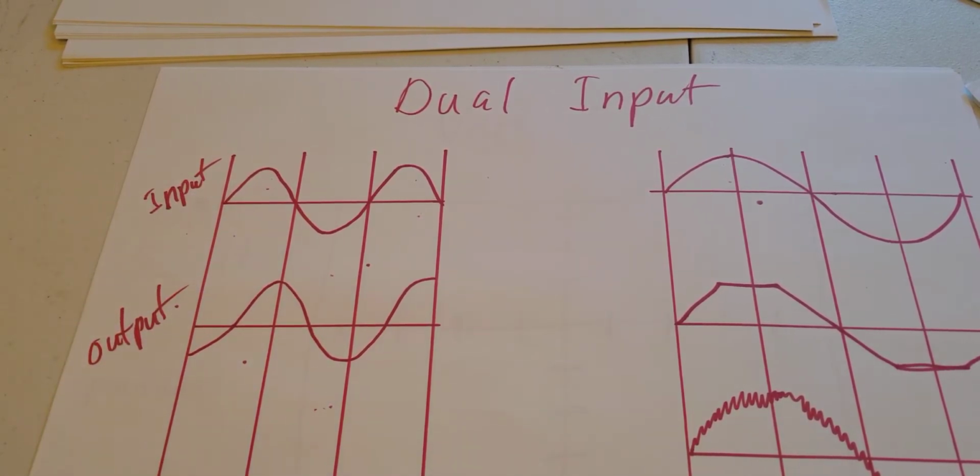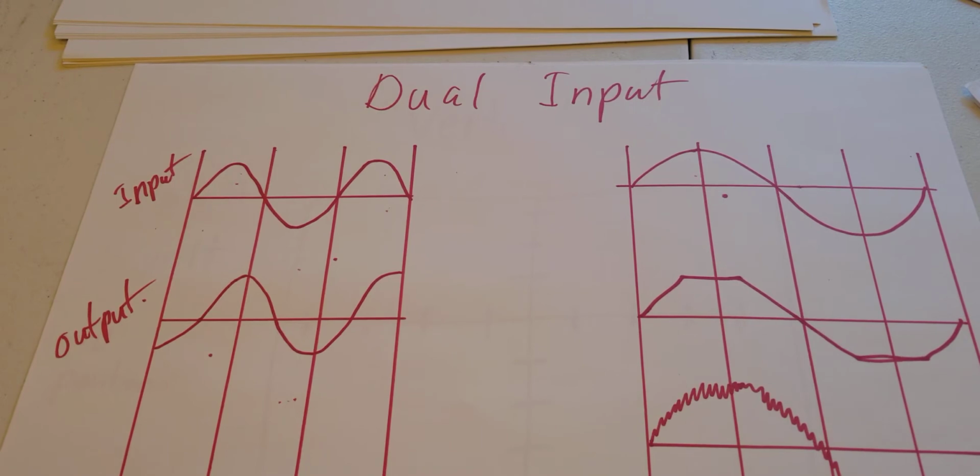So, for example, if you had a speedometer that puts out an electrical signal, there's a correlation between the voltage out and the speed. If you fed that through a differentiator, that would tell you the instantaneous acceleration at that moment. That circuit would have an output voltage that would represent that instantaneous acceleration.